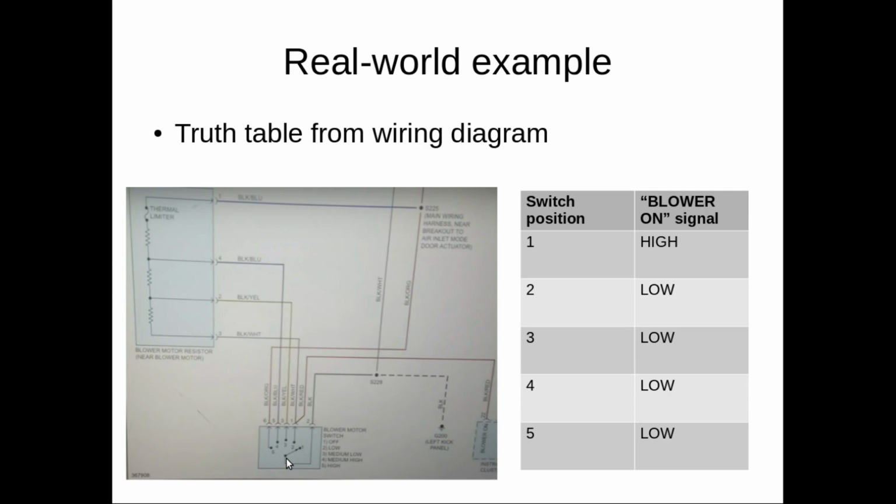However, things get interesting for switch position number 3, as this grounds pin number 2 of the resistor array, and this means that here the voltage will be 0, and thus the voltage will also be low in all this leg going all the way to the terminal again.